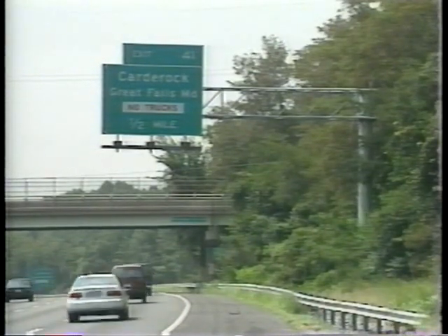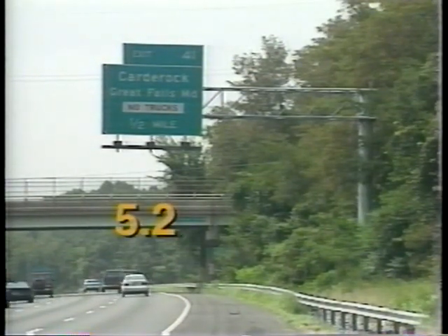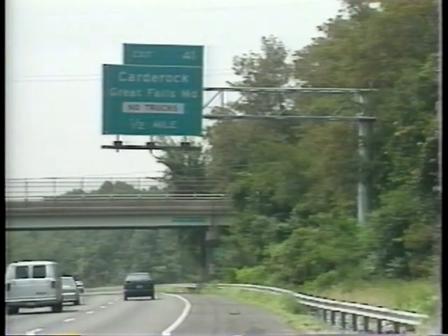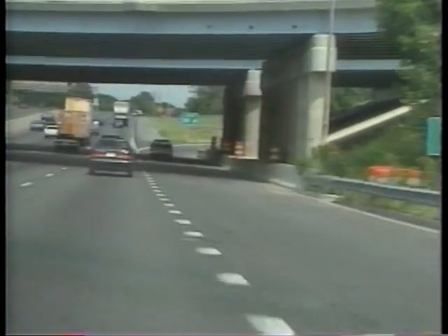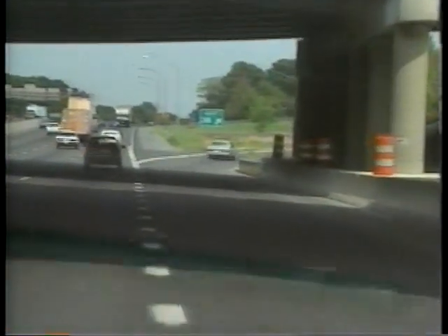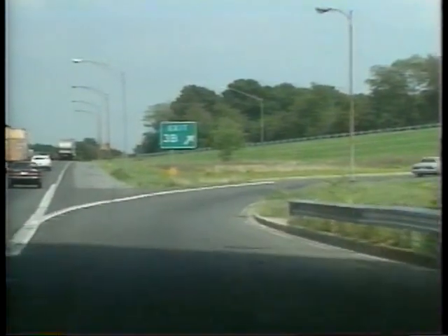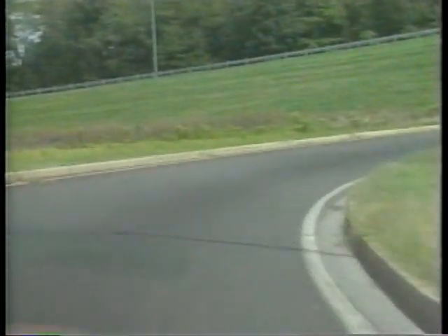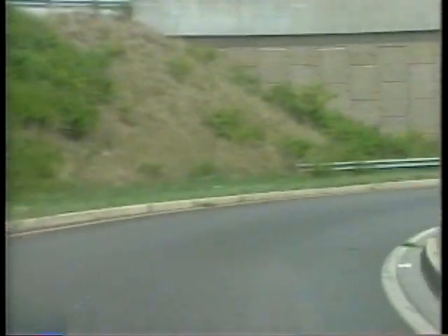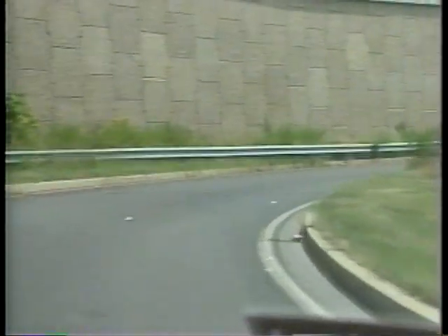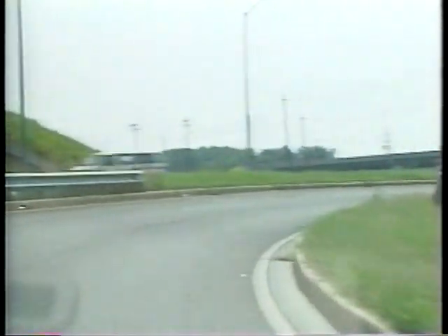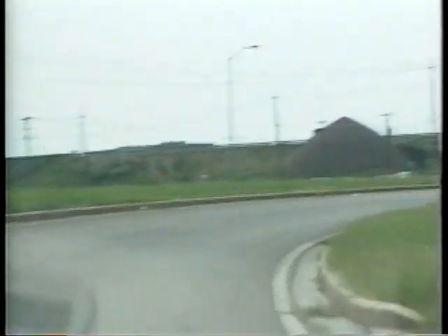Overhead signs should be at least 5.2 meters above the pavement. Certain bridges and tunnels may require lower signs. Interchange and interchange approach signs are placed to allow the driver a maximum amount of time to make decisions on which route to take. The driver sees the 3.2 kilometer and 1.6 kilometer approach signs. Then the 0.8 kilometer advance guide sign appears. At the exit, a gore sign guides the way down the ramp.